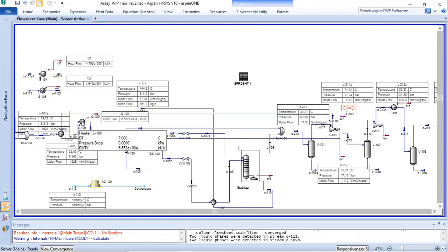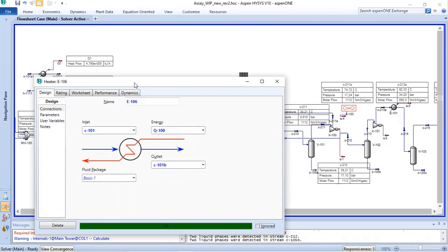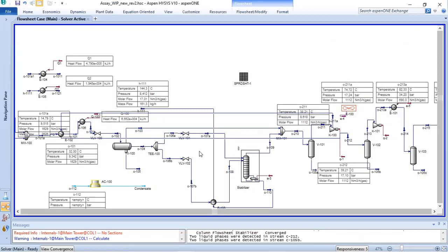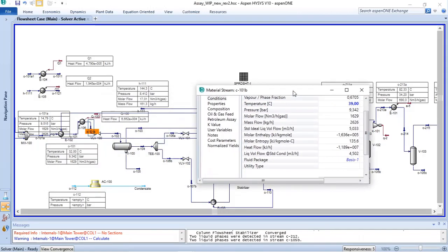So in this case I can have two things here. Because to start the plant, I need to have this stream at the desired temperature I want. So instead, in the normal operation, I will have the electrical heater off. During startup, I need to heat the stream because I don't have a compressor running, and I will change this stream like this.